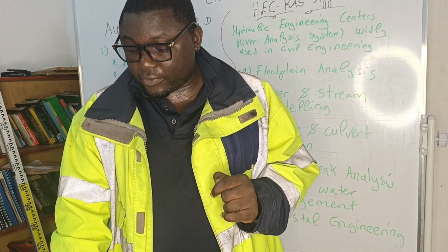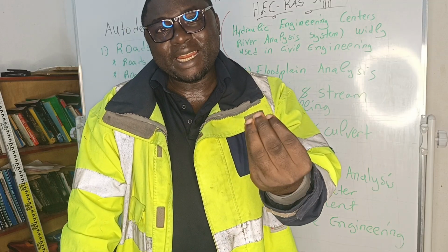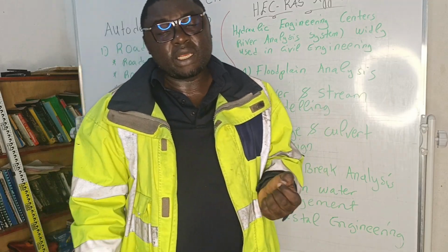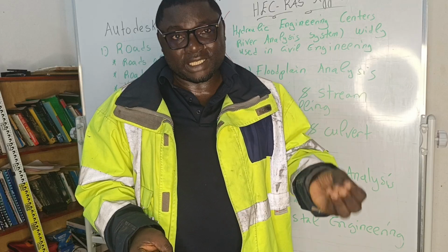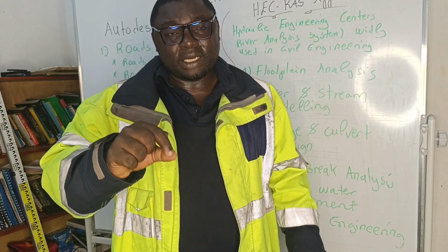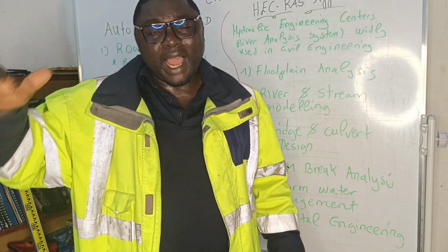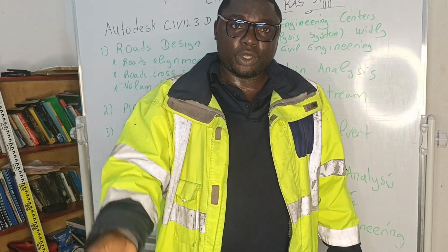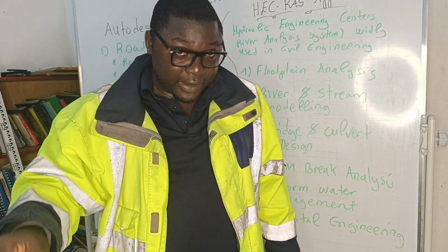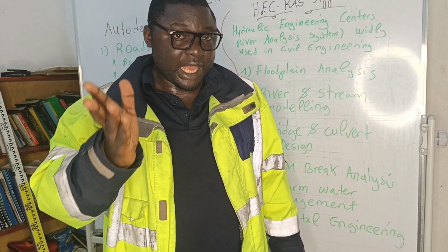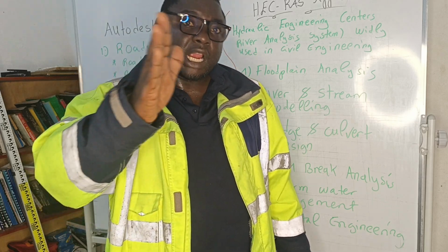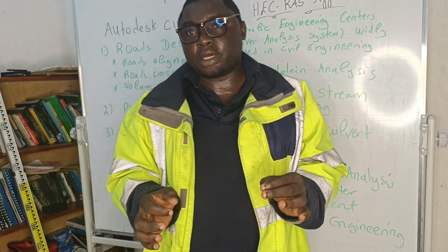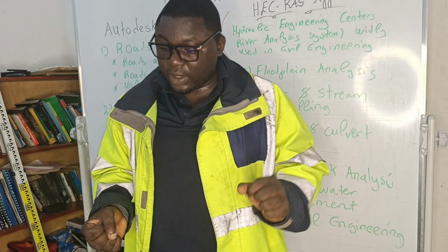Leveling surveys is this technique that is going to permit us to collect geospatial data, that is survey data that will help us to calculate the altitude of a point, or the height difference between points, and we are going to use the altitude or the reduced level. Those are synonyms: altitude, reduced level, elevation, to calculate the volume of earthwork. Okay, that will be chapter 1.